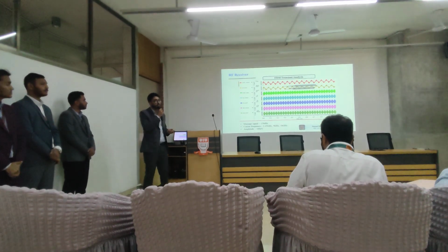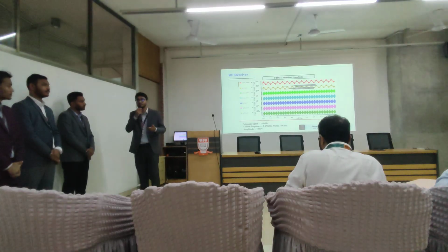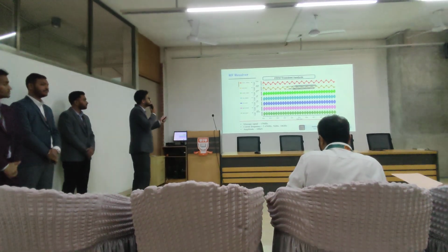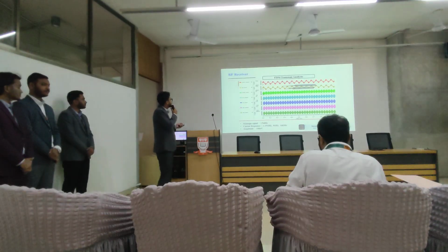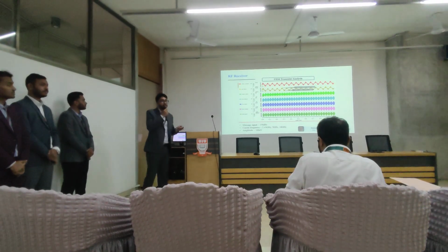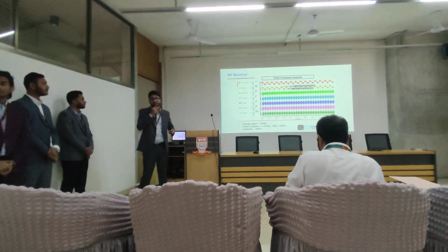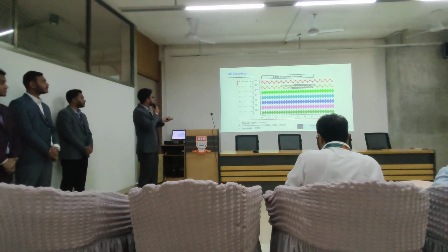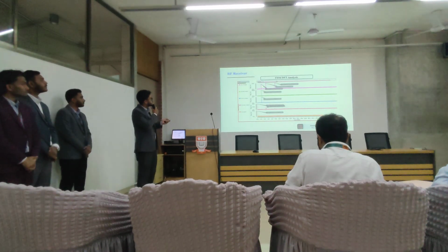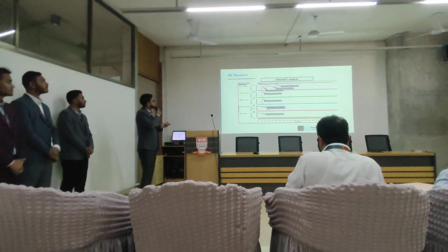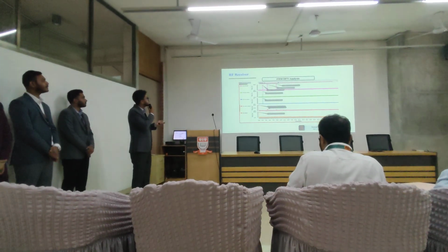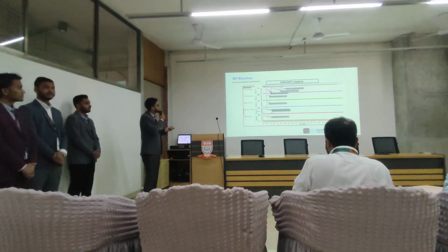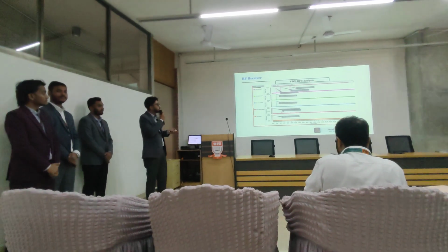Next, we analyze that our RF receiver only passes the 2.45 GHz and blocks other frequencies like 5 GHz and 10 GHz. So we did a frequency multiplication analysis, and in the DFT analysis, here is the message signal with the 2.45 GHz spectrum and the 5 and 10 GHz components. After the bandpass filter output, we get only the 2.45 GHz signal, which is what we desired.